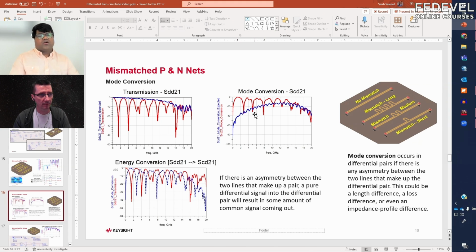Yes, and that's also again going back to the first thing, the realm of where you are coming from. Most RF engineers think in single frequency, but since this is a digital signal, the square wave is composed of multiple sine waves. So that's where you'll have to think about the entire bandwidth, and that's what we discussed previously: the rise time is more important than the data rate. Many times we ask, what's your data rate? Is data rate an important figure of merit? In digital, no, it's the rise time. How fast your rise time and fall time are determines the quality, the signal integrity challenges that you will get.